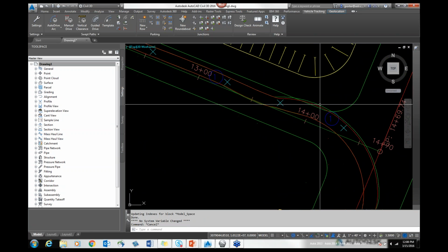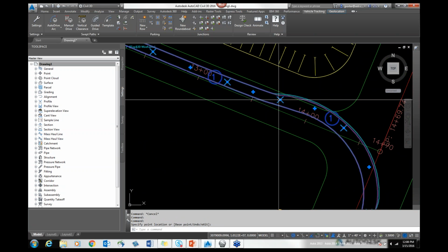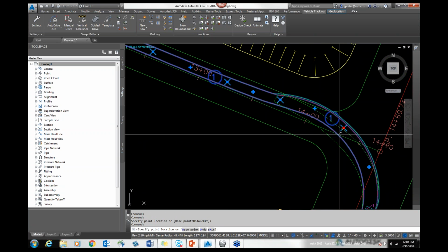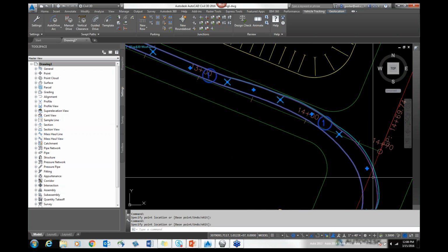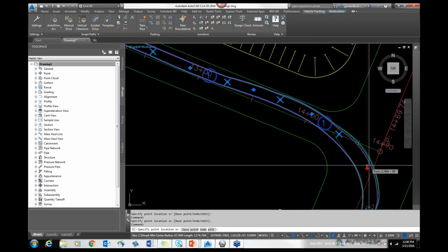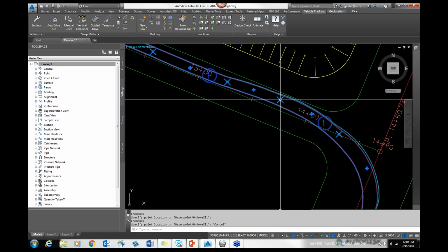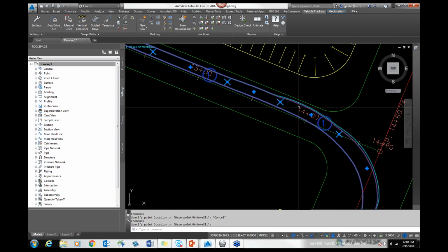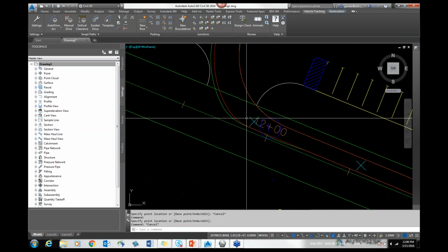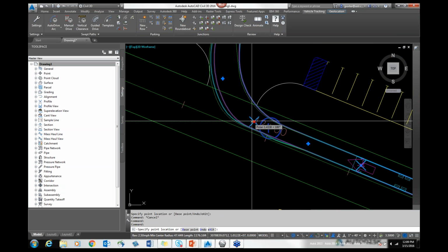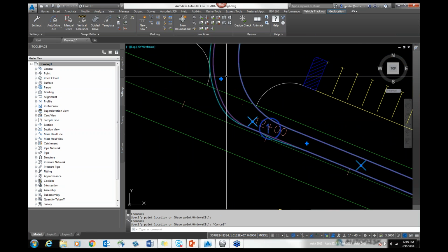Okay, I am infringing on here, so these X's along the way I can use to change that up. Let me pull this in slightly. That might be where we need to go. I can also use these plus symbols to add more. If I hover over this, I can insert a target point. These are the target points, where the person turning the vehicle will be looking or trying to get toward without hitting too much here. I'm barely making that, a little too close for comfort, so I might just make that in here, and I might add another target point right there if need be.